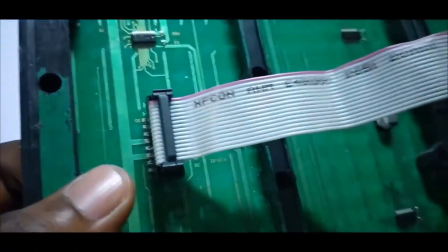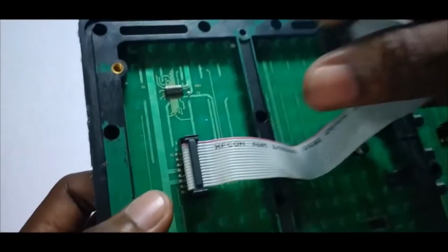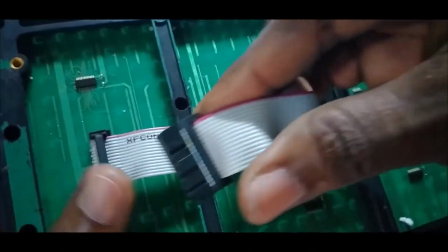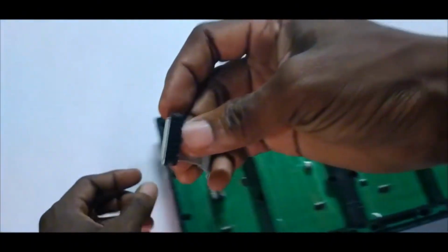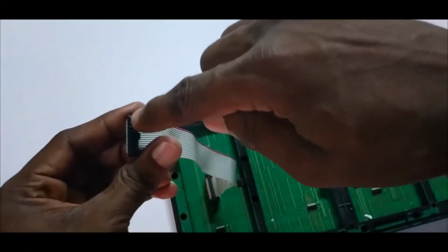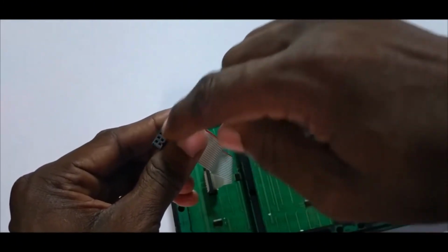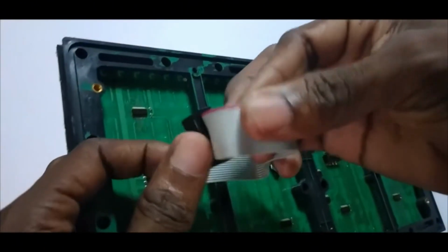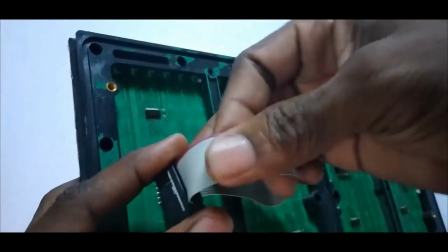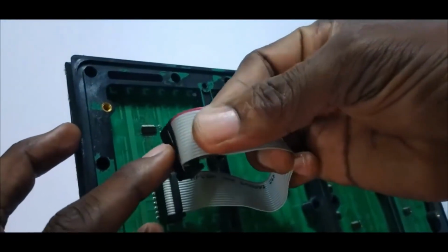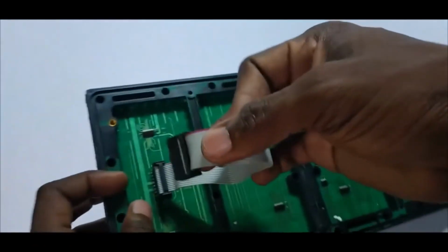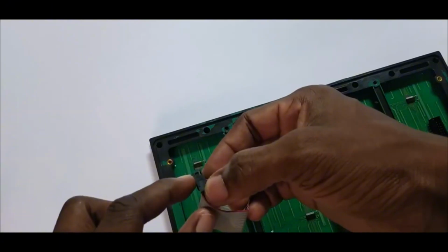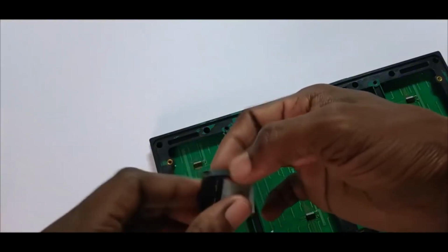It's fitted now. Okay, so to connect the Arduino board to this P10 DMD module, we connect the jumper wires to this female header pins. Because we have the ribbon connected to the board this way with the tab facing this side, it means that this pin here becomes pin 1 and this side pin 2. So we have it this way.